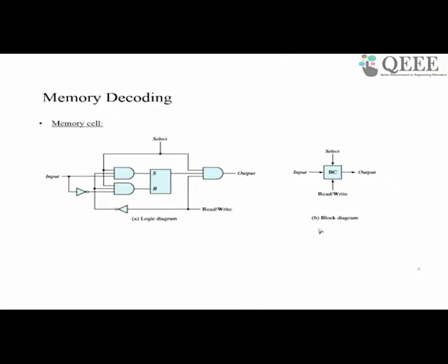Next we will see how the memory stores the various bits in it, and thereby we will see how the different technologies enable the bits to be stored in memory. We will see how conceptually a bit can be stored in a flip-flop, and then we will make use of it and construct a register which can be used as one location in a memory, and then we will put a number of registers together and construct a memory, and we will see how the locations can be decoded and so on. So we can see that a flip-flop can be used to store a bit.